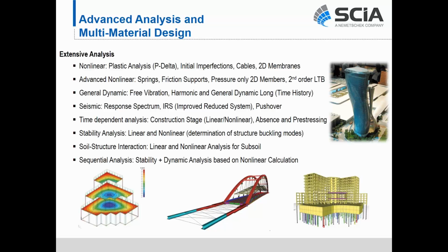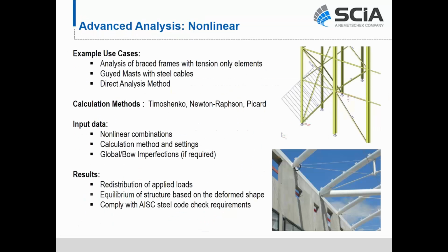We have what we call the improved reduced system. You can do pushover. Obviously, you can do a simple equivalent lateral force procedure. And then something we'll talk a little bit more about, soil structure interaction and stability analysis, both very important for industrial or tank-like structures.